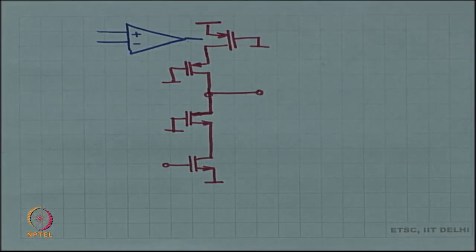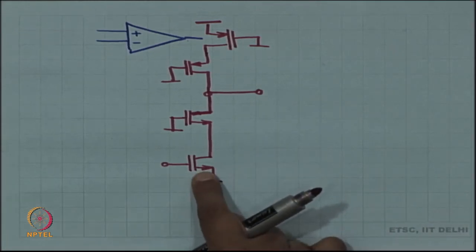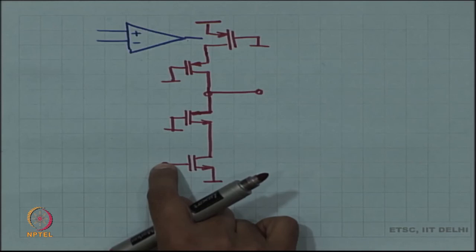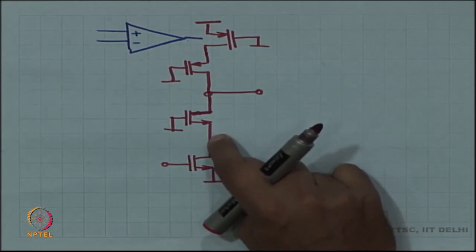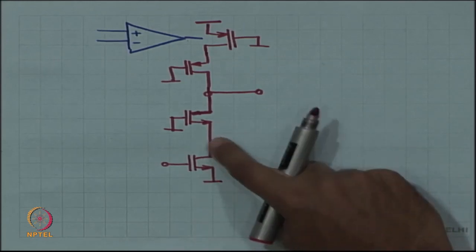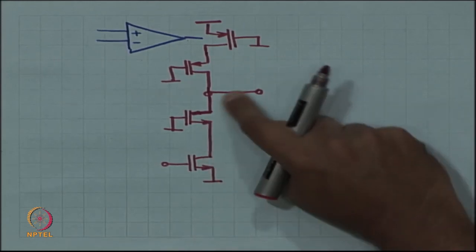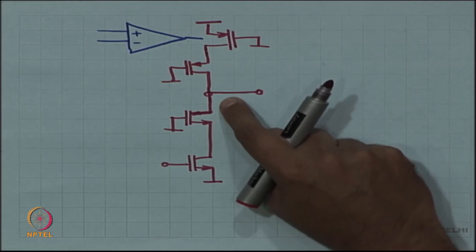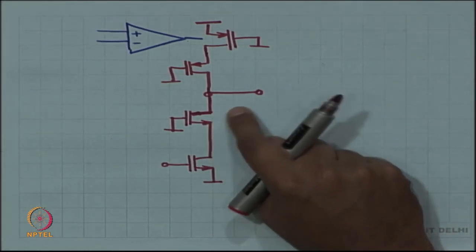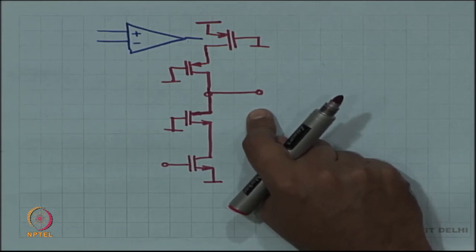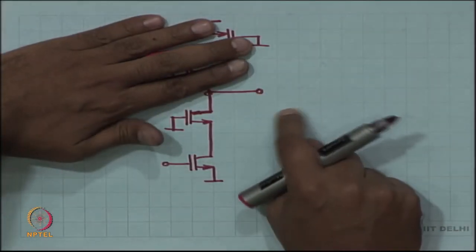At the same time, the short circuit current is approximately Gm of the bottom transistor. Why? Because I apply a voltage V, it produces a current Gm times V. This current has to choose between going through RDS and looking into the source of the second MOSFET. And looking into the source of the second MOSFET, it sees a low impedance because all of this is shorted, right.